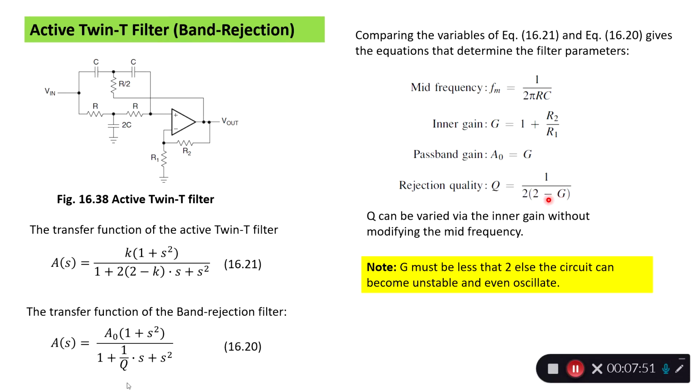becomes 2, we get a 0, and a 0 times 2 gives a 0, and then Q becomes very big, and a big Q means it's actually moving some complex poles, and we risk that the whole circuit becomes unstable and even oscillates, but typically it can go to one power supply rail, either the positive one or the negative one.